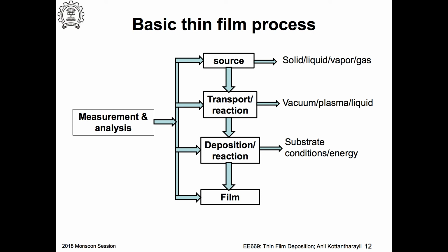And then, of course, for certain applications, if it is a metal, you want to look at the work function of the metal, and if it is a dielectric, you want to look at the dielectric breakdown strength, the interface between the dielectric and semiconductor, and so on and so forth. So you will do a lot of characterization, which is a very important component of research and development. And of course, in manufacturing, you would monitor not all things of interest, but at least some of the parameters like thickness would be monitored very routinely.